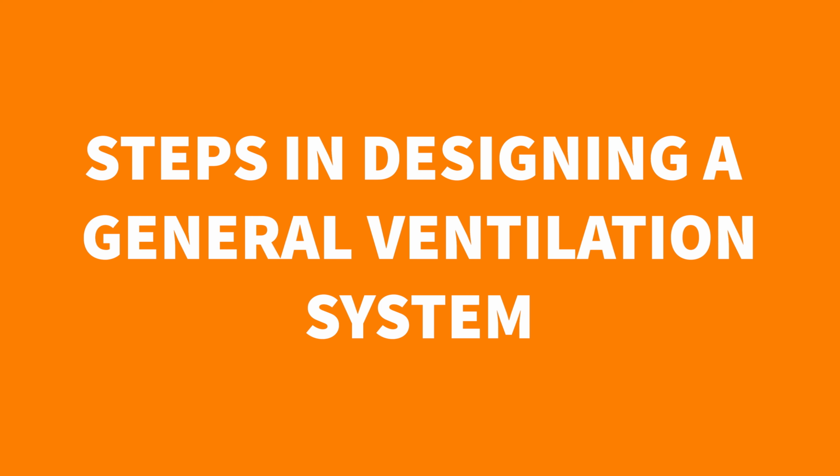So when we design, we need to decide, number one, what are we doing? Your determination of air changes per hour is going to depend on the heat and on the chemical suspension for general ventilation. Then, once we calculate the air change, we decide whether we want an exhaust air, whether we want a negative pressure room or a positive pressure room.